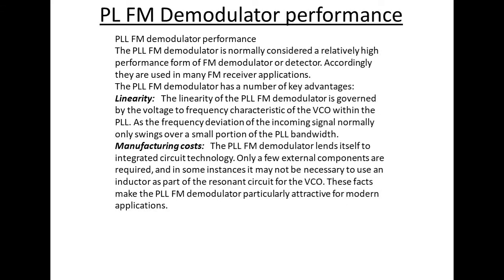Now let us take a look at the manufacturing cost. The PLL FM demodulator lends itself to integrated circuit technology. Only a few external components are required, and in some instances it may not be necessary to use an inductor as part of the resonance circuit for the VCO. This fact makes the PLL FM demodulator particularly attractive for modern applications. Now let's go to the next slide.